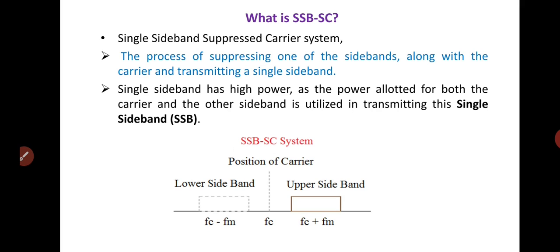If an amplitude modulated signal is transmitted, interference may occur between several carrier frequencies, resulting in steady audio whistles or beats. Noise also gets added to all signals in the communication medium or in the receiver itself. If the signal bandwidth is restricted, the receiver circuits are made with a narrower bandwidth.